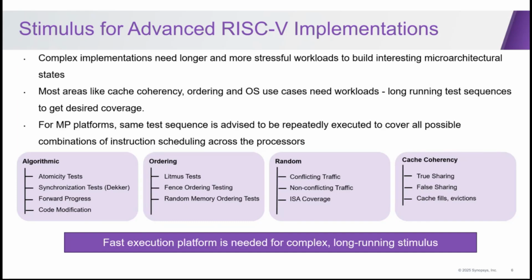All those kind of stuff, you can see they actually need a long test. When you run true sharing test, it doesn't mean, okay, I pick up one cache line, all the processors or the harts are trying to access this cache line on the same address. That's only the simplest scenario for true sharing.